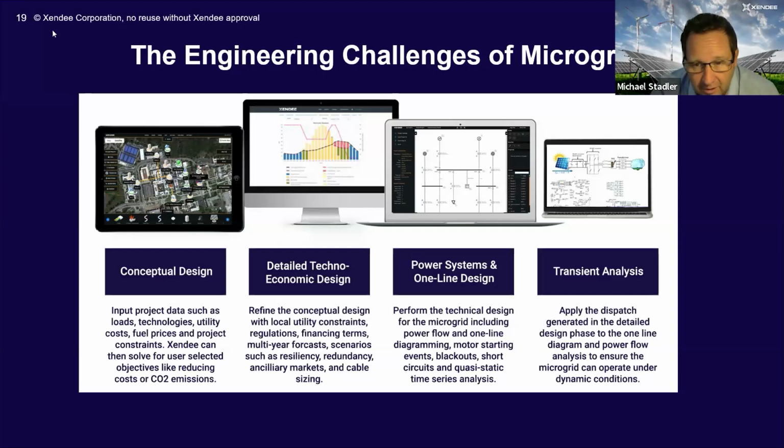Then, in the next step, when you get over that hurdle, a very detailed power system analysis might be needed, where you want to check if certain events might cause overloading for a transformer or cable. Maybe you want to do a fault analysis or whatever it is, right? And then in some instances, transient analysis might be needed, and most of the time this work is actually done by the vendor of the generator to figure out if the system is stable